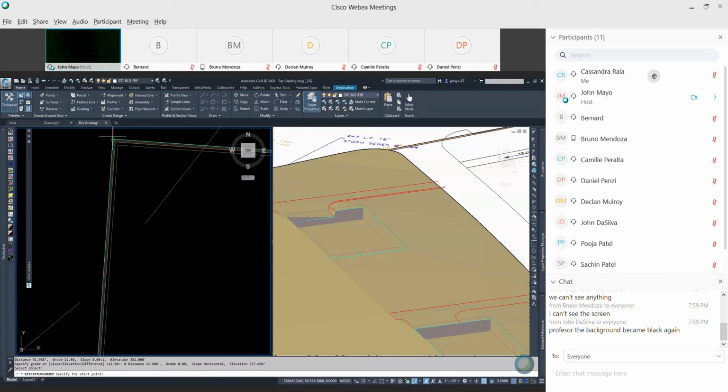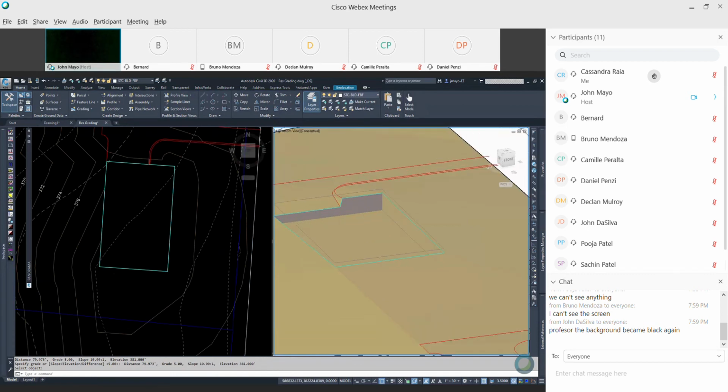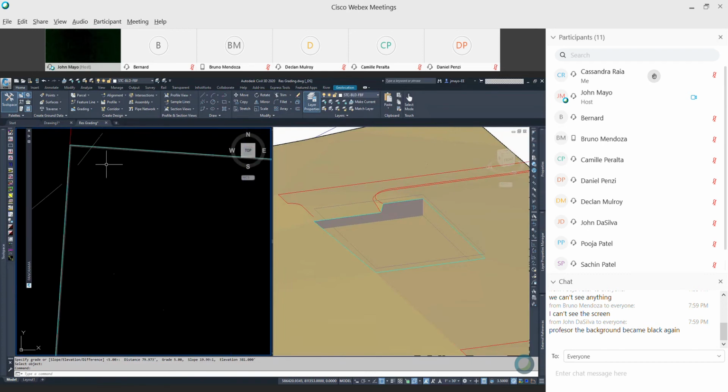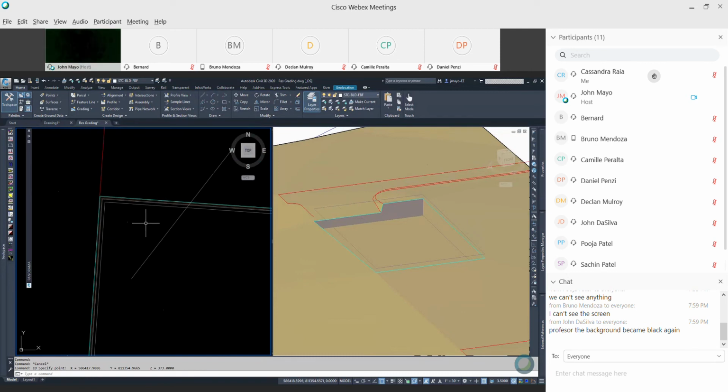And now we're looking at this grade here, and let's come across at 0 again. And we see how we are just beginning to make our elevation, but my driveway is a little bit above. I've got my 4 feet there. I really want to shift that driveway down a bit. So what elevation do I want? Let's see if that works, working it up from the other way. And what I'm doing here is my grading, as you see, is an iterative process. I need to try a scenario, see how it's working, and then continue from there.